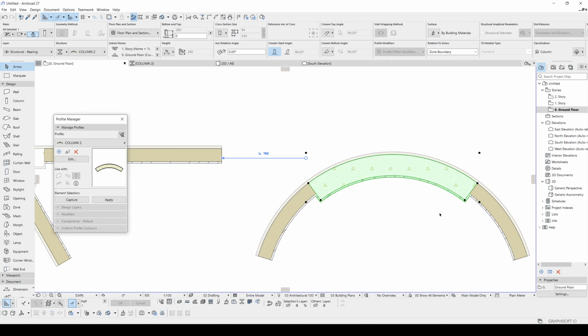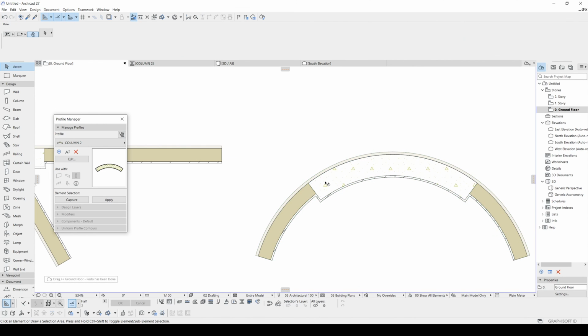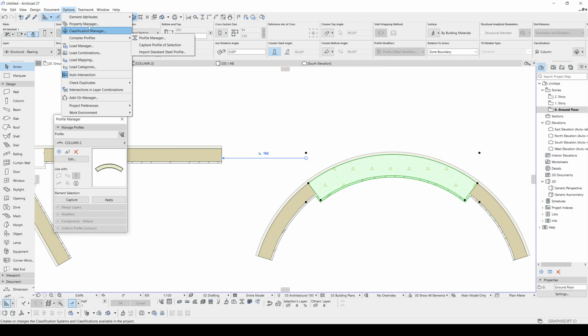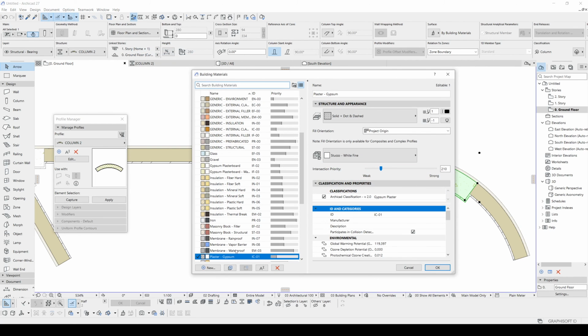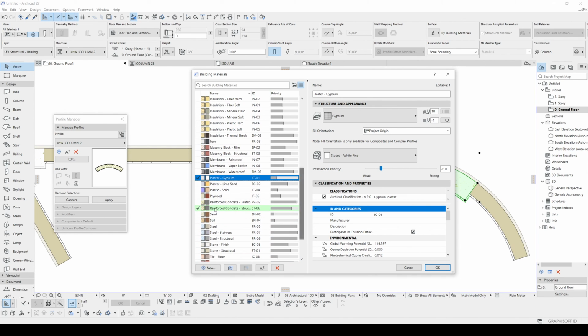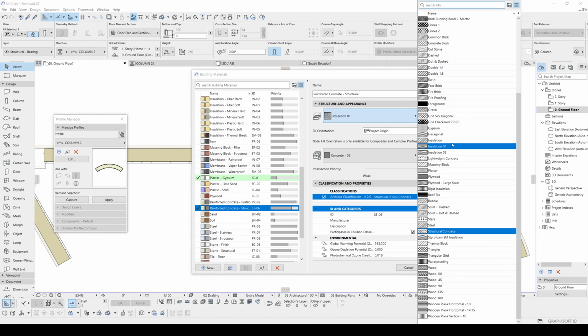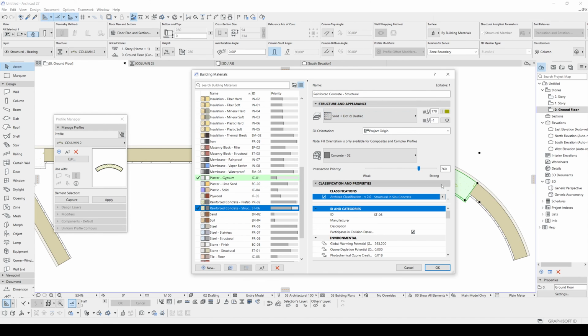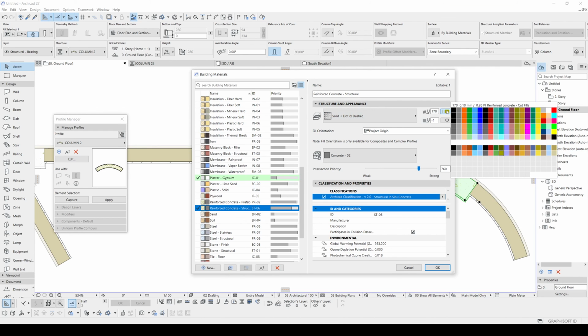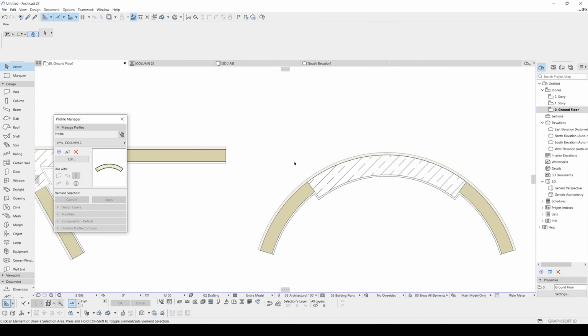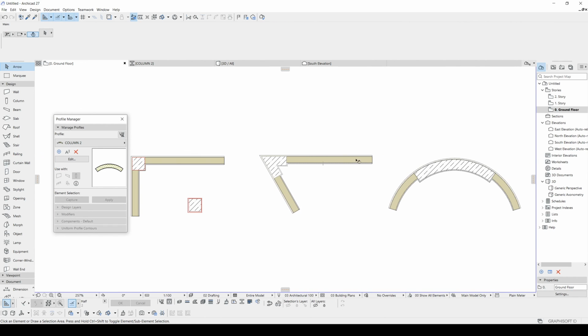Oops, we have changed the plaster. Let's fix that. Now, this is plaster gypsum. This was gypsum. And this type, if we go to the top, we will see this reinforced concrete as we did before. We will choose the solid dot dashed. And our fill type was 1. There we go. It's way more elegant right now.